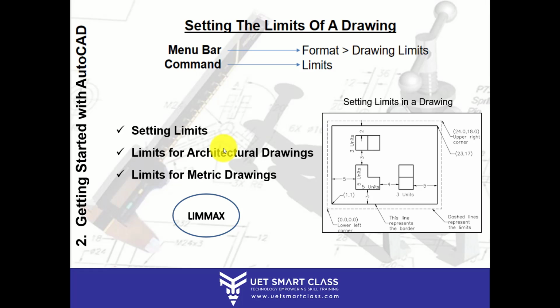So for example, if your sheet size is, in simpler words, 10 by 10, then the x limit would be 10 into 48, 480, and the y limit also will be 10 into 48, which is 480. So here the scale factor is 48, and accordingly the limits will be 480 by 480. Or you can convert inches into feet as well by dividing by 12.